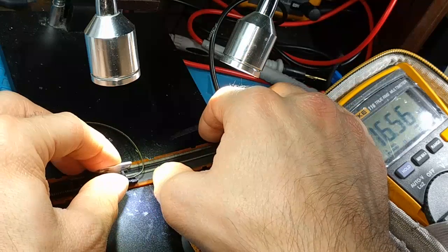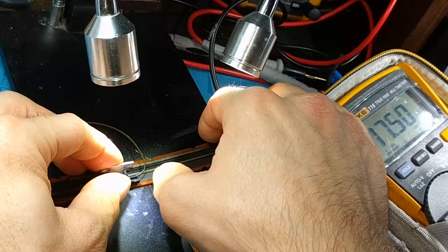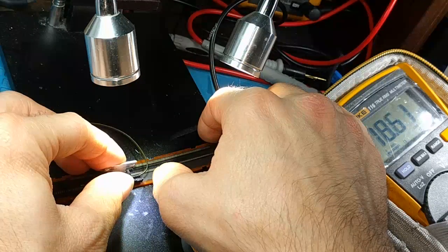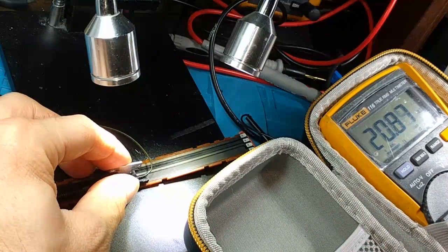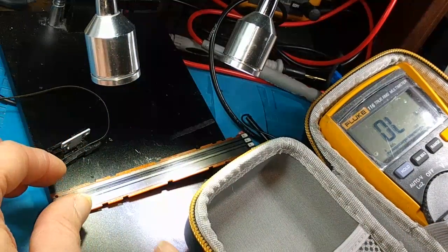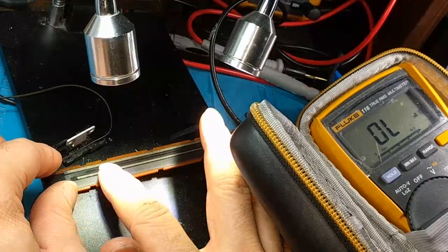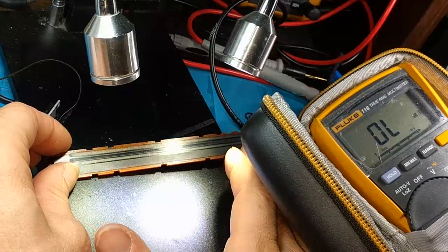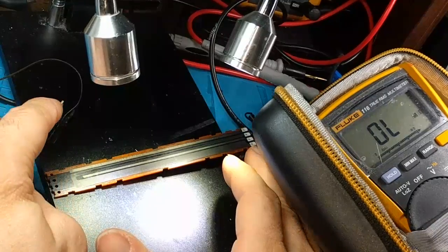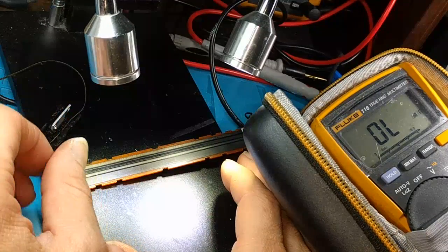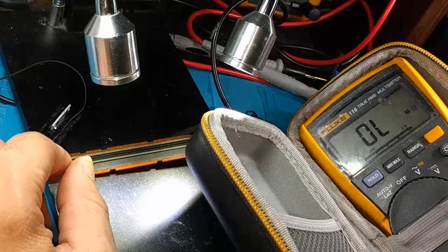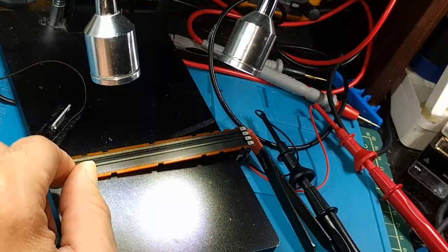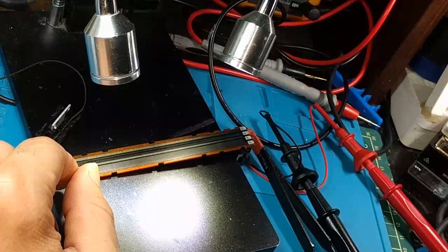And you want to get it to where you can actually see 17K, 18K, 19K, 20K. So it's going up just ever so slightly, which tells me that unless there's some clear dead spots in the track that I can visually spot, and I can't, the track is probably fine. The teeth are actually working quite well too. You want to make sure you don't have any scraping sound when you do this, of course, because that'll damage that resistive track as well.